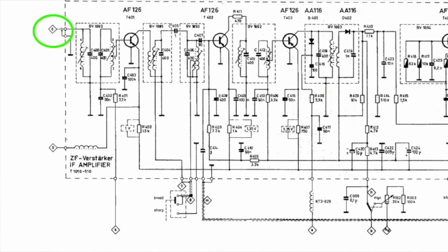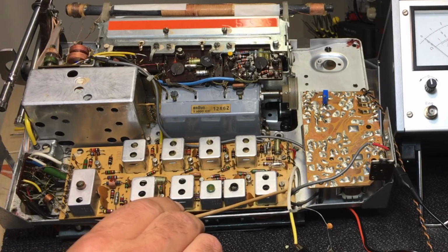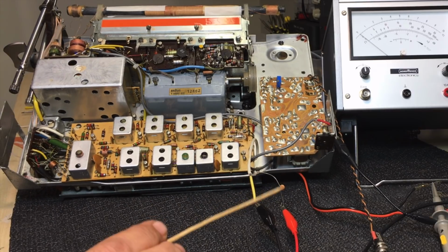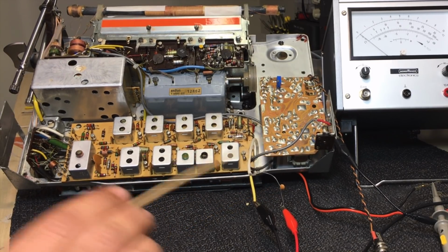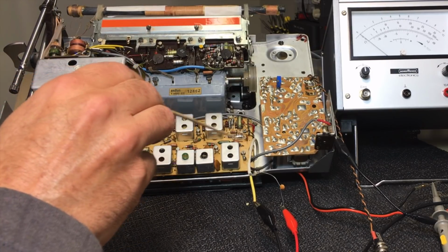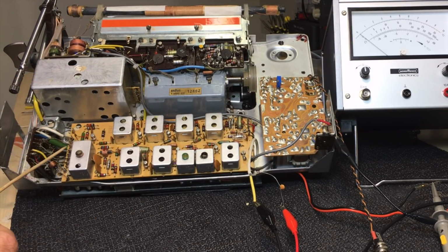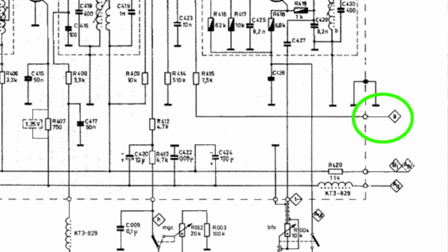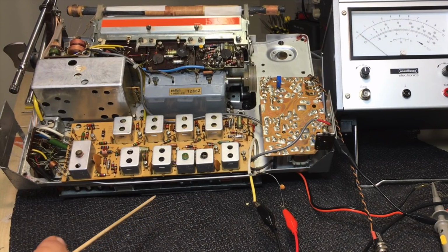It goes onto there to point number 6. And ground, and they suggest you connect a signal generator with a 455 kilohertz carrier to that signal through a 4 picofarad capacitor. And I happen to have one here. It's a very small capacitor, which is fine. So the signal goes in there, and it comes out here at pin 9. It's this one over here. And this then goes off to your audio selection switch, where it selects between AM audio or phono audio, and then that goes into your power amplifier and you get your result.